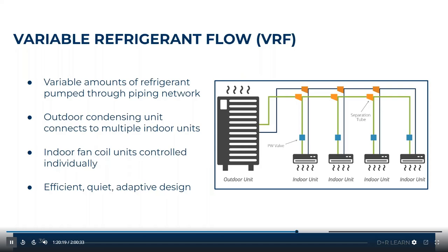But because these systems utilize refrigerant, this can pose challenges with code violations for specific sites, especially where you have occupied space by human occupancy in certain spaces. This can hinder your installation of a VRF system just because you have piping that will be traveling overhead of an occupied space.